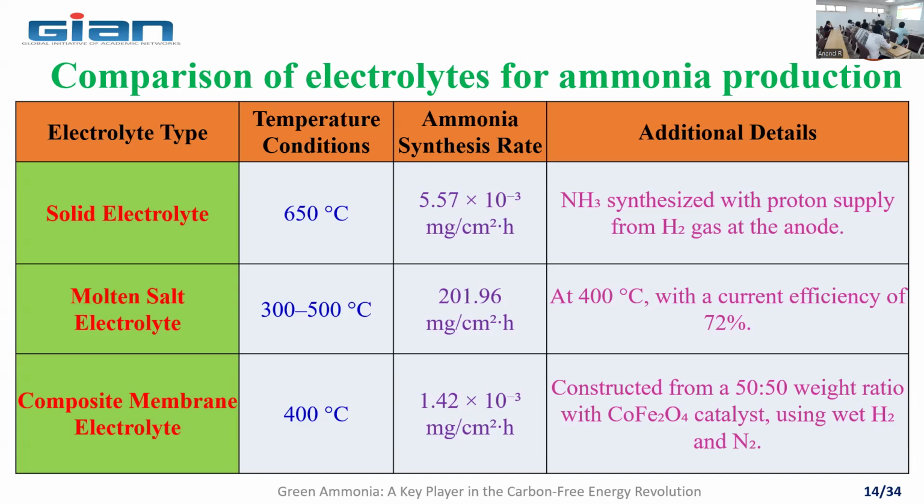Then for the membrane electrolyte, normally we call it the polymer electrolyte membrane. Normally you come across the PEM fuel cell or membrane electrolyte. There we are using the membrane called Nafion membrane. It will permit only positive ions, not negative ions. But in order to increase the reaction, we are coating some kind of noble catalyst on the membrane to further enhance the reaction.